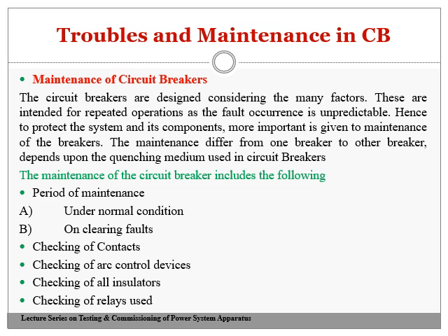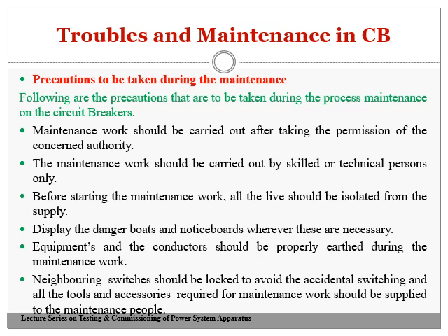The maintenance of a circuit breaker includes the following: the period of maintenance under normal conditions, on clearing the fault, checking of the contacts, checking of all control devices, checking of all insulators, and checking of the relays used. As we have seen already for all other equipment maintenance, here also some precautions are to be taken during the maintenance period. The following are the important precautions to be taken during the maintenance of the circuit breaker.